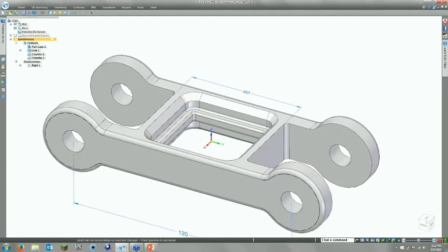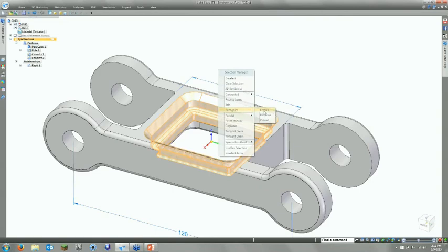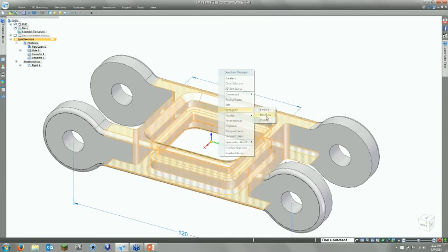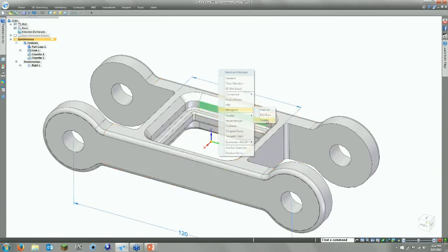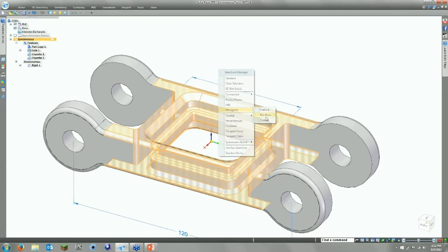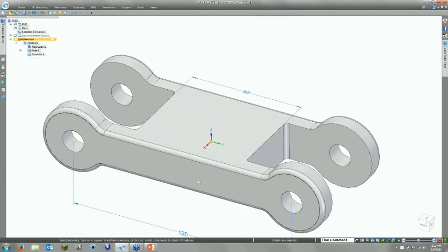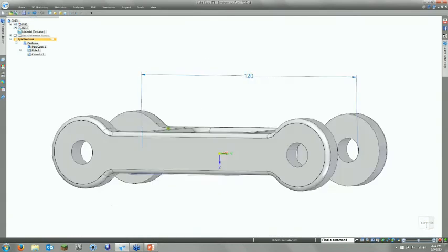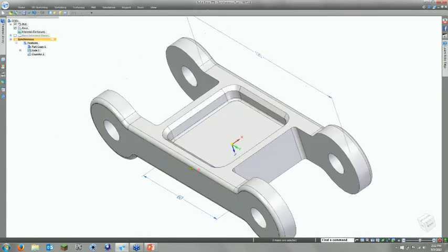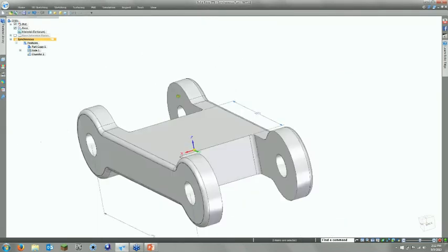area. So what I'm going to use is a selection manager tool, which allows me to recognize types of features. I didn't create this as a feature, but it looks at the geometry, interrogates it, and says, hey, the design intent was this as a feature. If I wanted this to be just a rib, it looks like that's taking the entire middle section out. I don't want that. Maybe a cutout would work, but it looks like it's going to leave the chamfer. So let me go ahead and just grab this feature and delete this, and let's see what it leaves. If I turn it over, you notice we still have the pocket on the bottom, but we have the flat face on the top.